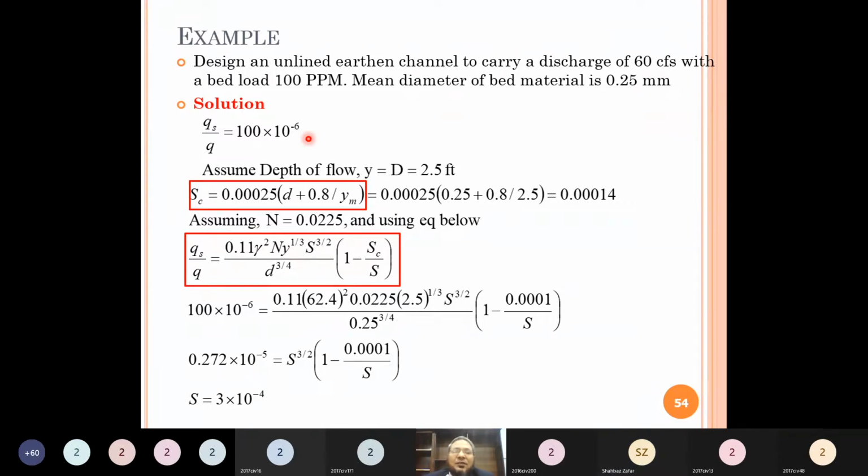Okay, all right, so it means you should check this calculation again, maybe there is some issue. It should not be more than that. We have to keep the longitudinal slope slightly less than this critical slope. Then it will not move. Okay?